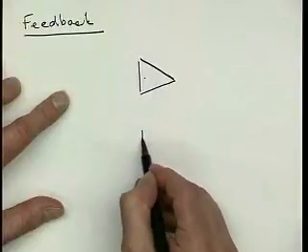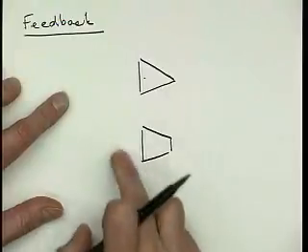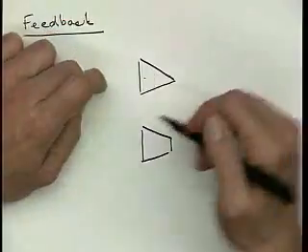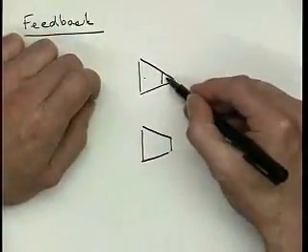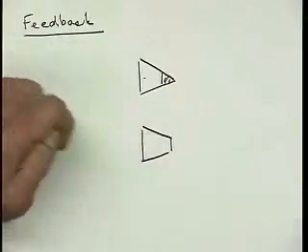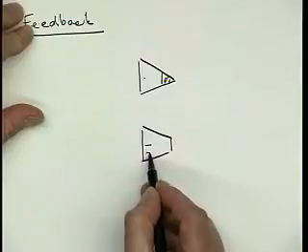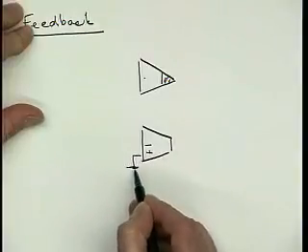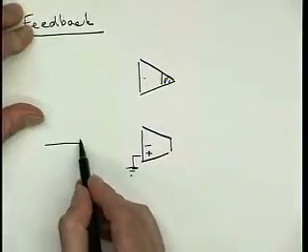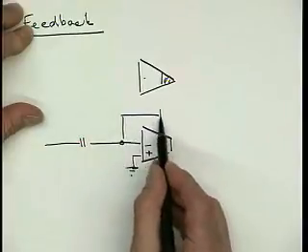When I'm not absent-minded, I draw this symbol for a transconductor and this one for an op-amp. The idea is that this triangle is the 1x buffer that isn't present in the transconductance amplifier. Usually I'm too lazy to draw this extra terminal here, so I just do it once. So, let's try capacitive feedback.